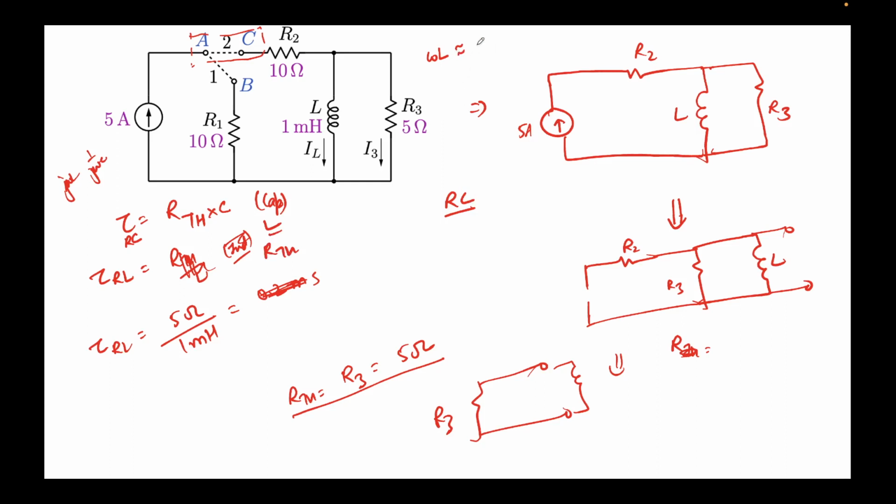Yeah, so that's why I was coming to that. So this is 1 upon omega C, this. So this is also Z and this is also Z, right? So I was going to say the multiplication should give Z square. That's the trick to remember. The multiplication should give Z square. So LC should be equal to R square dimensions. So you multiply by R over here, and then you can rearrange. So that's why RC should be equal to L over R, right?